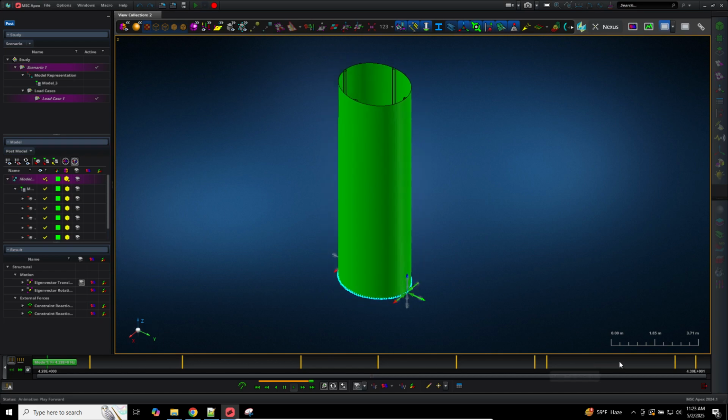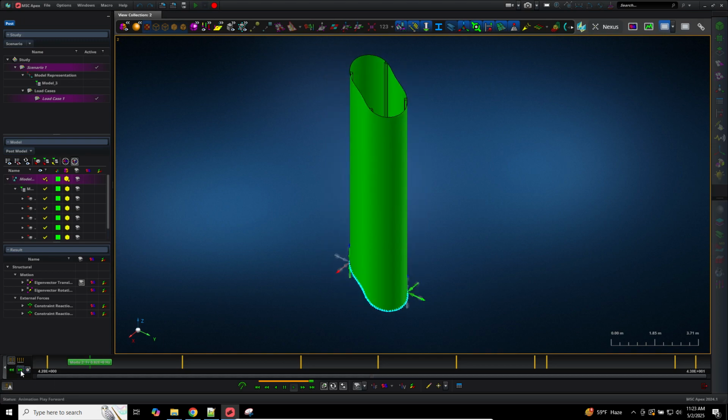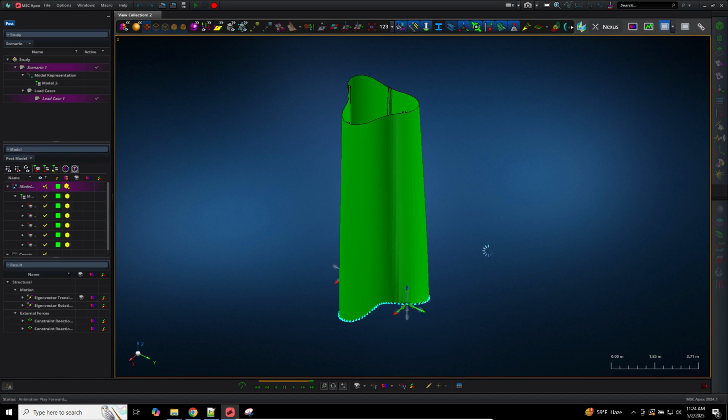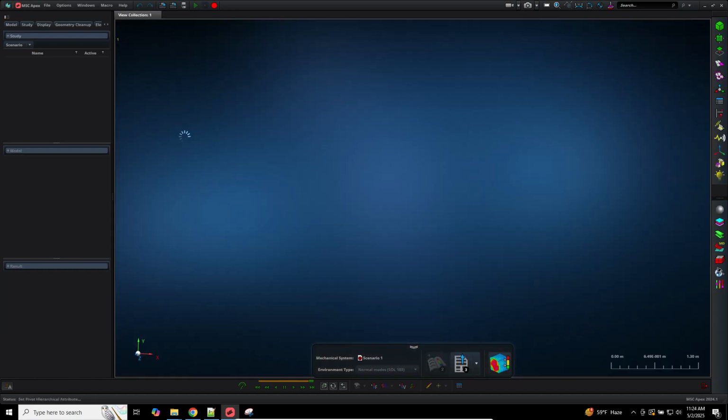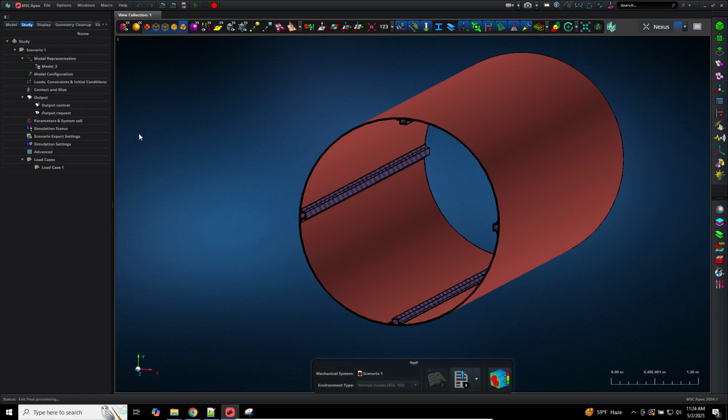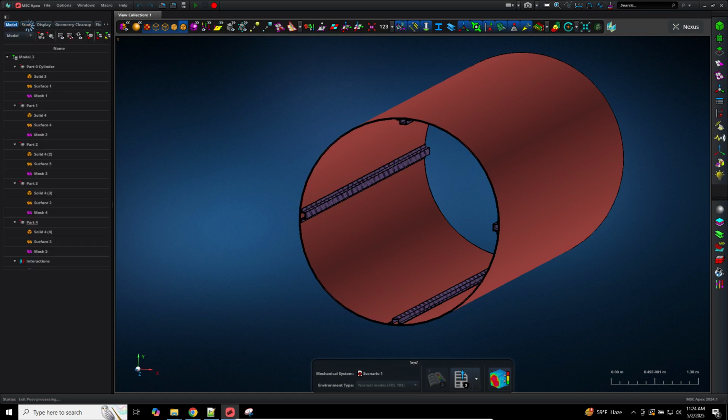So here in this horizontal bar, all the modes, here in this bottom left, I can click on these arrows. I can jump between the different modes and say, okay, this structure looks like it's properly supported. I have non-0 hertz here. Let me close this. Now let's try and perform a statics analysis for those 2 load cases. So let me delete the old scenario.